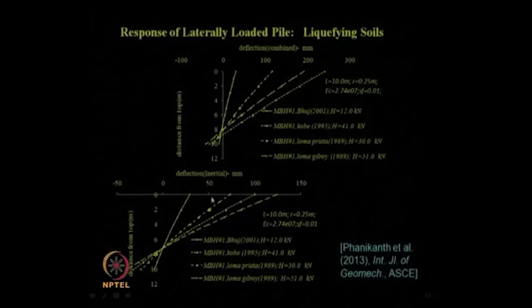But suppose with that, what you are doing? You are rectifying the possibility of liquefaction in the soil, but the lateral load that is coming, the inertial component, still remains. Okay? You are not controlling that, whereas for this particular site of Mumbai, the Mangalbadi site, the major component of deflection comes from the inertial portion.